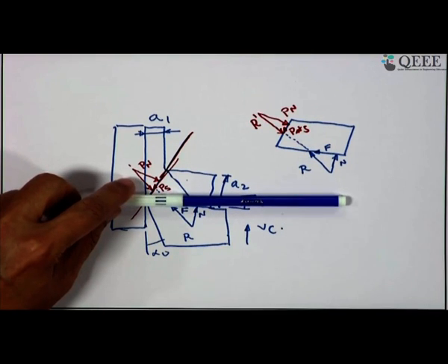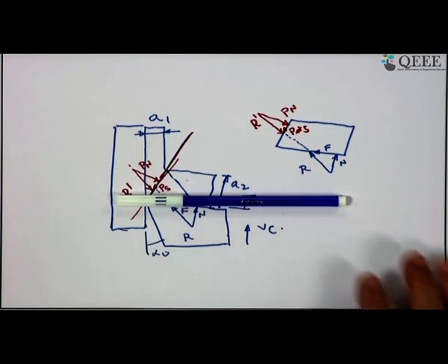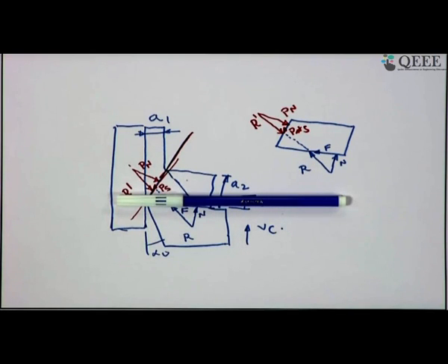Now, in this direction the whole job will be deflected, and this deflection means you cannot ensure accuracy on the job. Depth of cut will keep on changing, and it is held between centers, or a center and on the left hand side with the help of a 3-jaw or 4-jaw chuck. So, rigidity of the whole system will keep on varying as the cutting tool moves from the tailstock side to the headstock side, and you have a deflection pattern, and ultimately what you get cannot be a cylindrical surface.